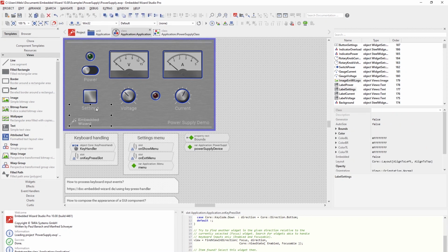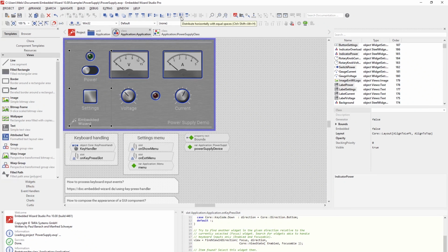Next to that alignment, maybe horizontally, maybe vertically, on the left side, on the right side, on the center, there's also the functionality now to distribute elements, either to make them in equal space or to keep equal space in between for that selected view. For example, by selecting those elements and changing that, every middle position of that selected view is now distributed in a proper way. It changes a little bit depending on the view. If you have views with different sizes, this makes more sense than this simple example, but it gives you a little bit more the feeling of how to distribute views.